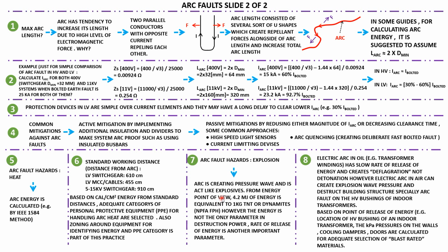Normally the explosion is looked after in great detail by the switchgear manufacturer. Switchgear manufacturers know this phenomenon very well. When they want to manufacture a switchboard which is arc rated, they really want to control the explosion wave and pressure wave, keep the structure intact, the switchboard intact, and direct this pressure out of the switchboard. So this is the main thing that switchboard manufacturers deal with to make a switchboard which is arc rated.